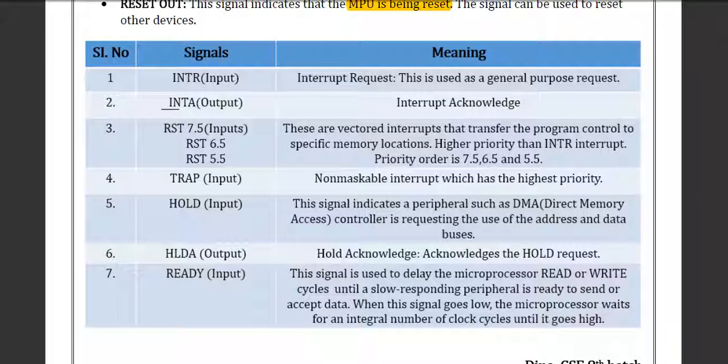Here is the description of other pins. INTR is the input, INTA is the output section. Trap is an input section, hold is also an input section. In the hold acknowledgement and ready section, hold acknowledgement is the output and ready is the input signal.